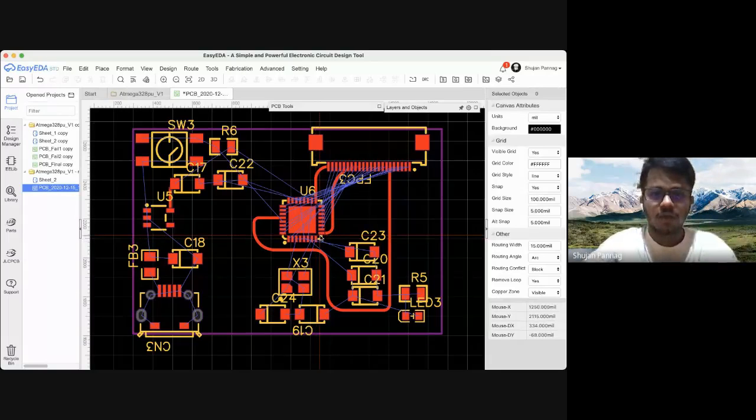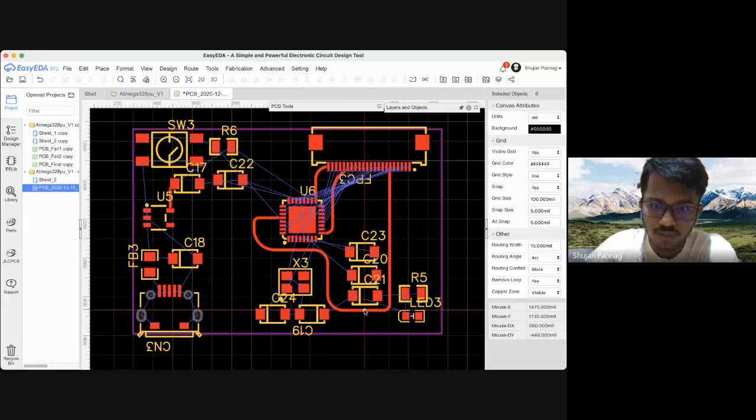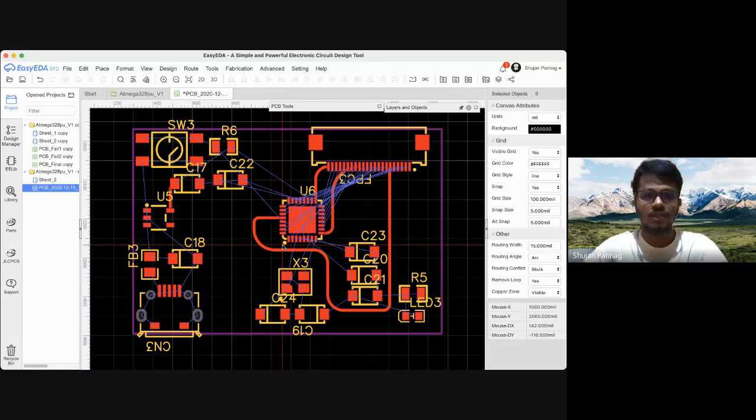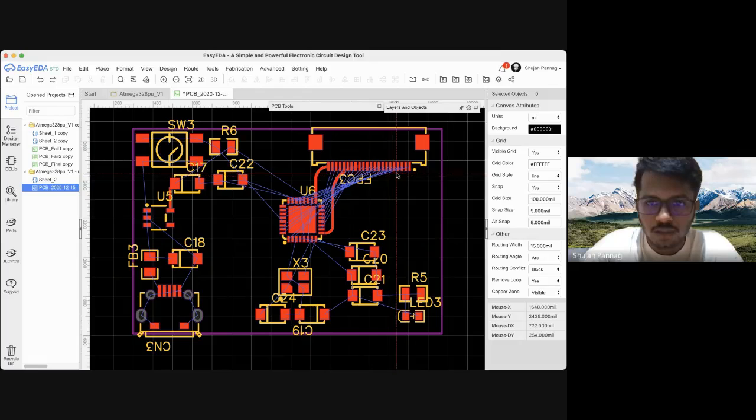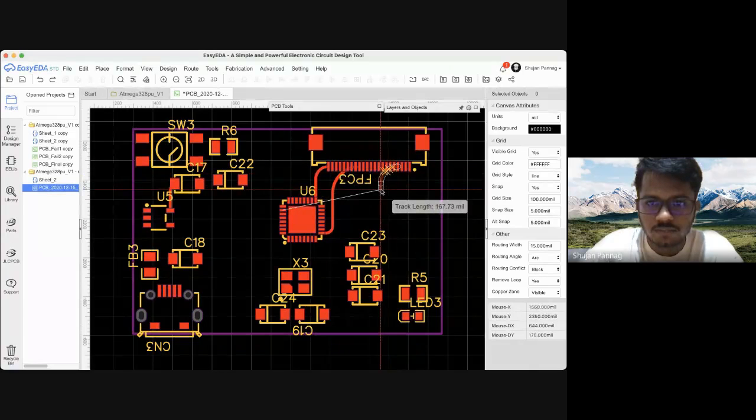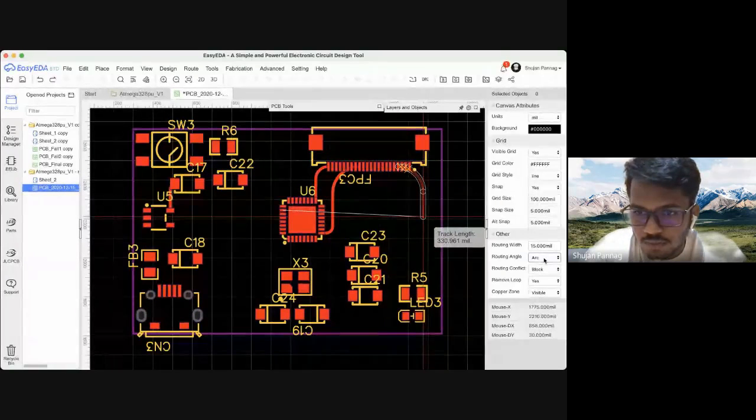So how do you go around that? And another thing is you're doing a very long track path. So you're creating a very high impedance for the current to go through, and also you're creating new stray impedances and capacitance, which is again wrong. So how do you go around that? What to do is you use vias, because this, I'll just change the angle to 45.